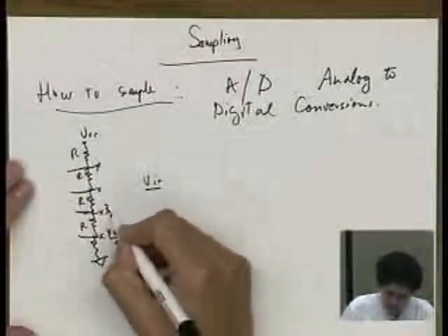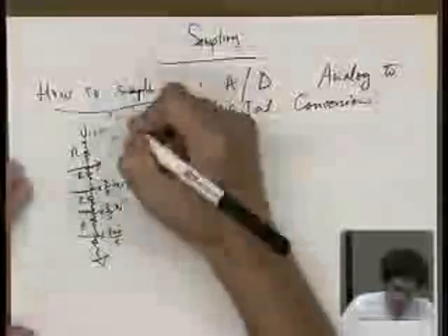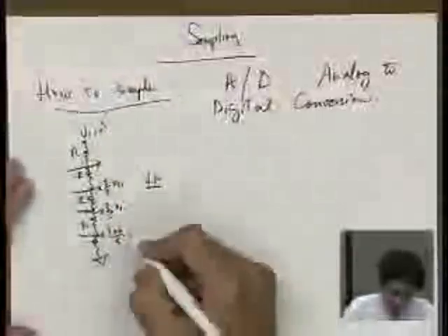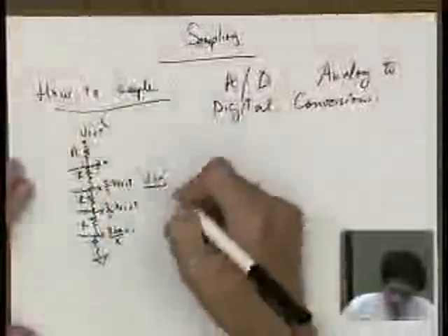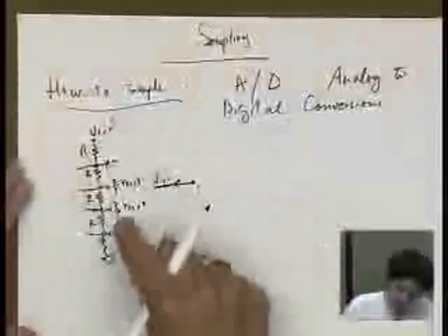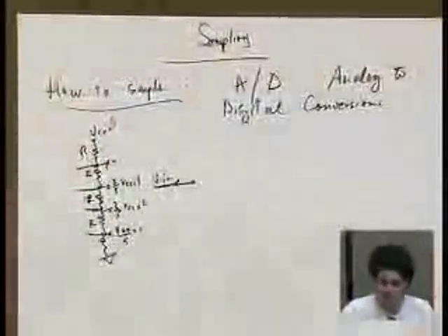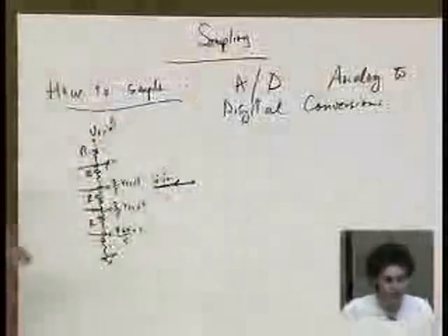That's 2/5 of VCC, etc. That's 3/5 of VCC. VCC is a fixed voltage, for example, 5 volts or something. So this is going to be 1 volt, 2 volts, 3 volts, 4 volts, and that's 5 volts. And you start with your signal coming in that you want to decide what it is, and you compare it to one of these, and you figure out which bin it falls in, and that's the discrete representation of your signal. It's a lot more complicated in reality.